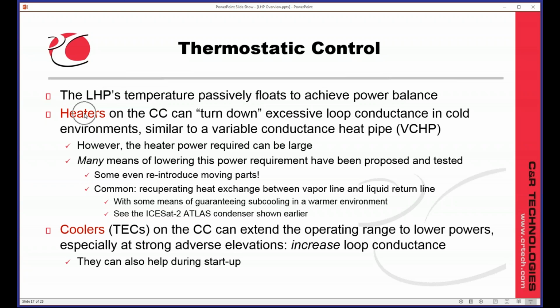But just the same way you can apply heat on the condensation chamber, you can apply cooling. I mentioned that before. And that actually increases loop conductance instead of decreases it. And it also turns out to be a nice companion to an LHP because it also can help on startup, as I'll show in a minute.